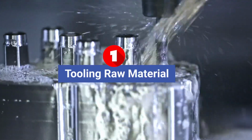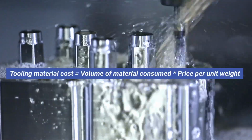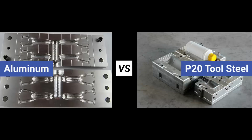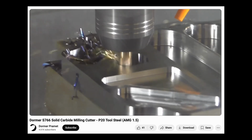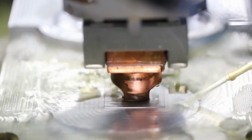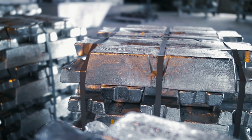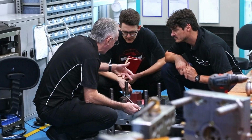First, we have tooling material. The tooling material cost is calculated by the volume of material consumed and its price per unit weight. Let's compare, for example, an aluminum tool against an equivalent tool made from P20 tool steel. Since the volume of material consumed is, of course, exactly the same, and aluminum is lighter than steel, that should mean that the aluminum tool is cheaper, right? Not so. Aluminum is more expensive per unit of weight, so the total dollar value works out to be about the same for the two.